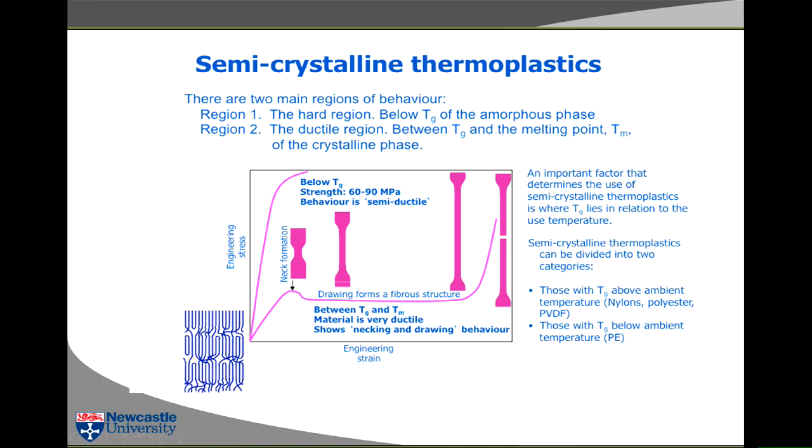So you are actually creating very strong materials. And in some areas of polymer technology, like in tire cord and in synthetic fibres, that can be used. In pipeline technology, we don't use that, but it's just interesting we should know. So the material will neck down, the neck will propagate all the way along the sample until all the sample consists of necked material, and then the load will go up again and the thing will fail. So that's what the stress strain curve looks like. And that's important because this necking phenomenon determines how the material will behave in a pipe.